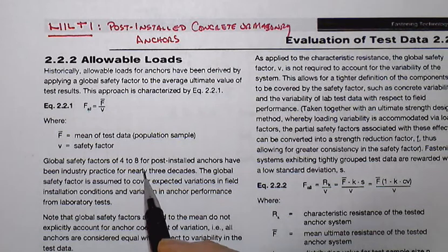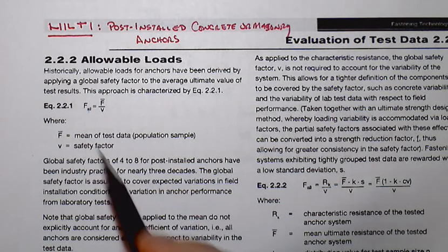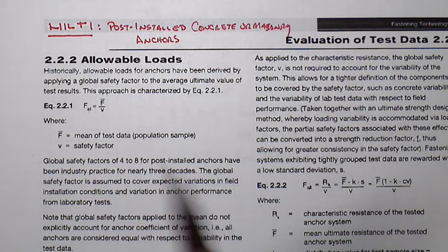Particularly when you get into masonry, you might have a larger factor of safety as well. The other aspect is that it incorporates the notion of risk: the consequence of something bad happening tends to be more catastrophic, because of the brittle aspect of the failure modes, than it might be for some of the ductile failure modes. So that's just the basic setup here that you need to keep in mind.